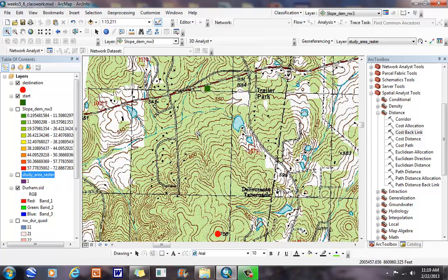Okay, if I go up this way here, you can see the contour lines are really close together, which represents high slope. Okay, if I go up kind of towards this direction here, you can see that it's less of a slope. Okay, if I go across the lake right here, well, that's great because there's absolutely no slope associated with the lake, but we can't do that. Okay, and when we go through and set up our parameters later, and some future things, we can set this area up to be no data. We're not going to do that for now.